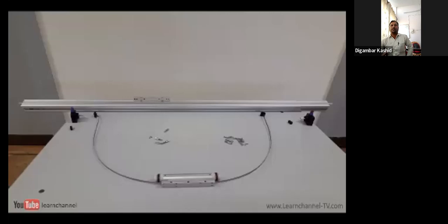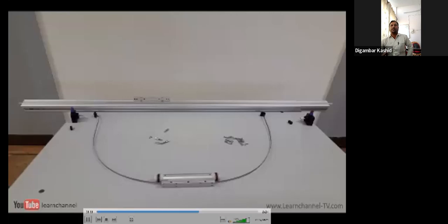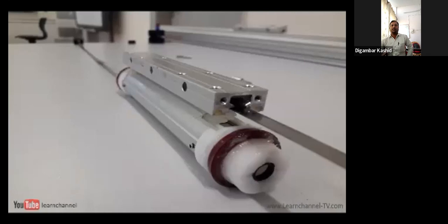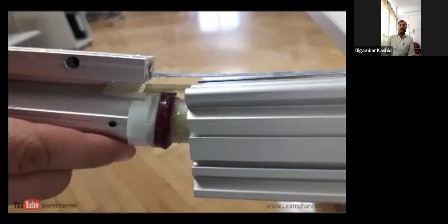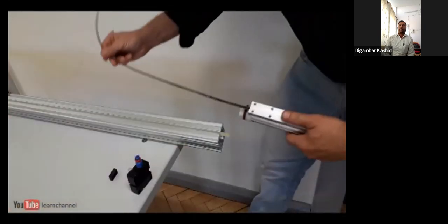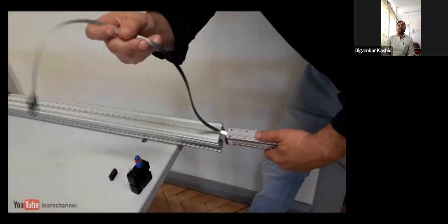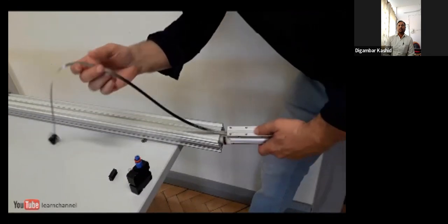Here you see a band cylinder totally dismounted and fit together again. Inner and outer bands may wear over time as they stretch. As a result, you can get air leaks and loss of air pressure. It is up to the maintenance to replace these bands, especially for expensive cylinders.